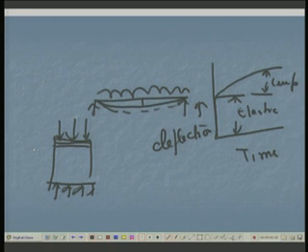Since we are not looking into the details of this, I can quickly give you an analogy. Creep is something similar to consolidation of clay. Clay takes a very long time to consolidate, and it is something similar, with a much lesser effect of course, in the case of creep. The gel, water, etc. are redistributed and thereby result in time dependent deformation or deflection, although you have not increased the load.